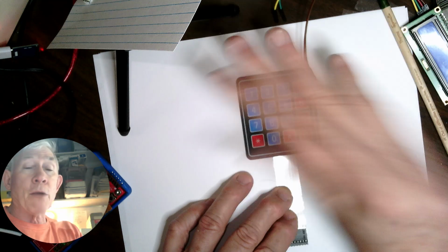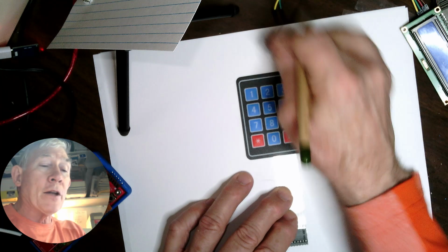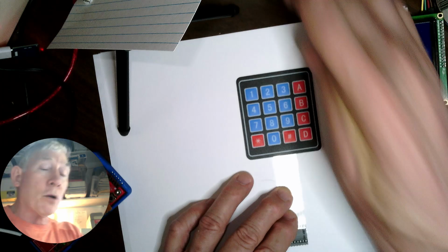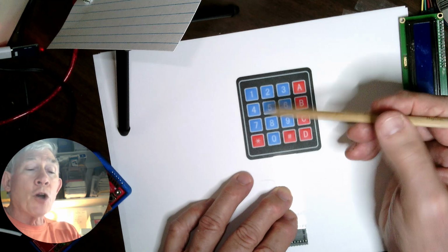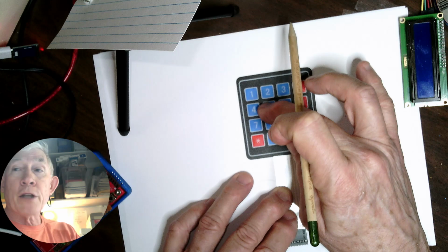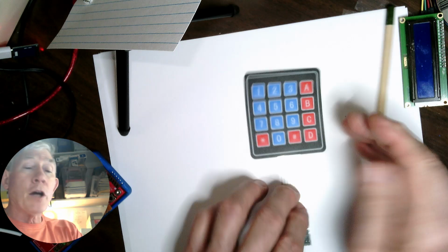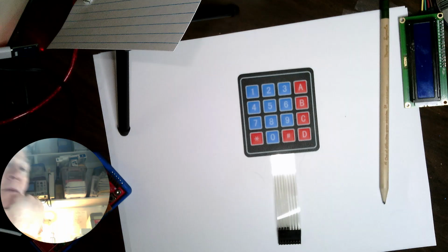They could be either one. And as you move things around with your hand near the pad, you might induce a voltage on that wire, and it might go from reading high to low or low to high. You don't even know. So you have to pull them high, and then we drive them low when the button shorts the columns and rows together. So now that you've read the column and you've read the row, now you know if there is a column and a row showed up, and now because you know the column number and the row number, you can figure out which pin it was, and that's how that works.